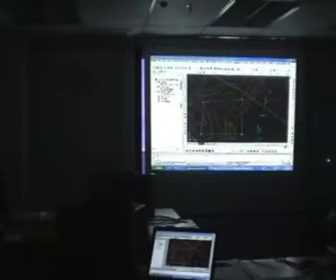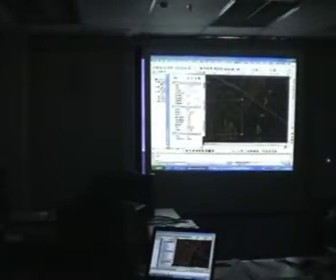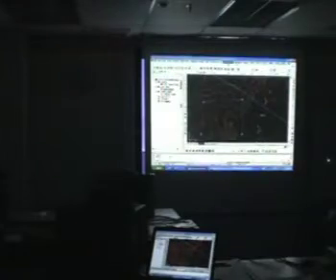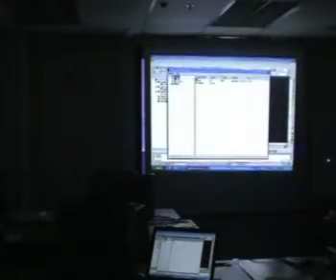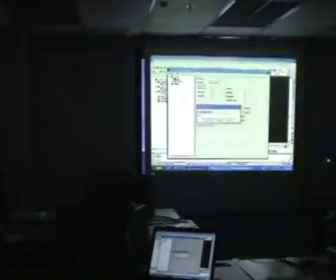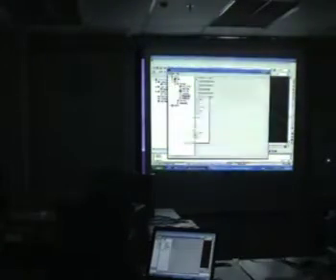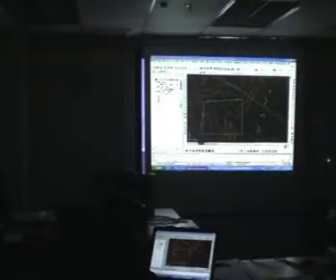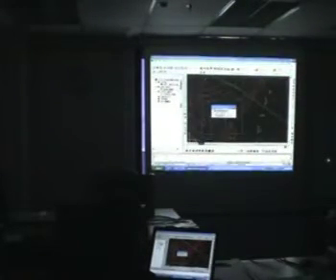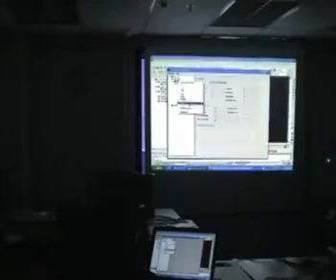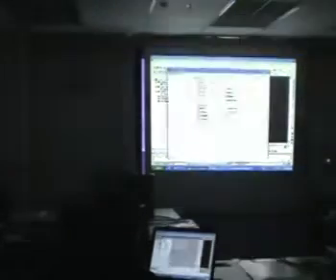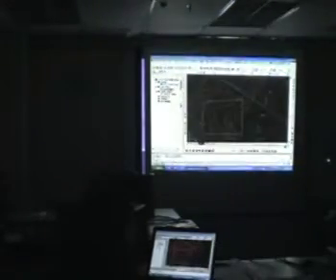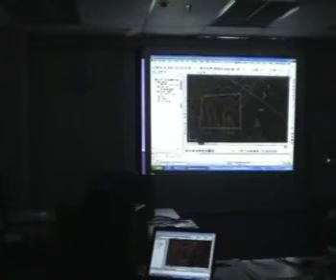This is a very simple platform, so I'm just going to draw a square, say 35 meters elevation. I'm just going to define this as my proposed level. Okay, no slopes, nothing. I add this in as a break line. Just build this. Okay, so now we already have a platform.